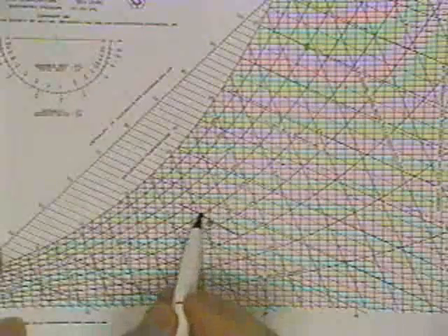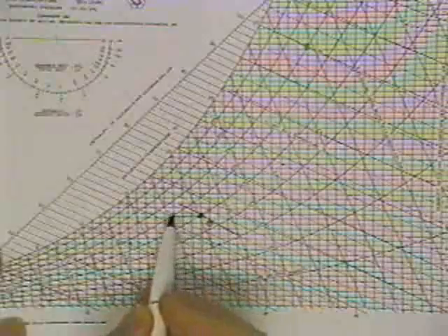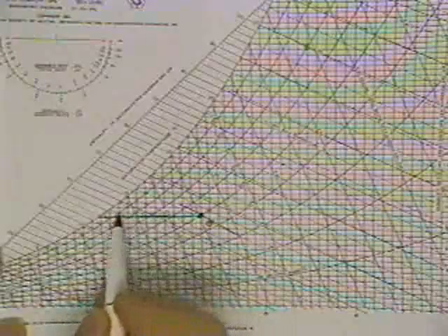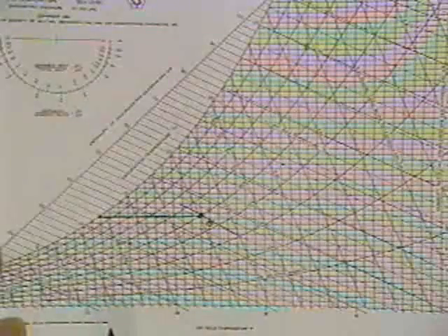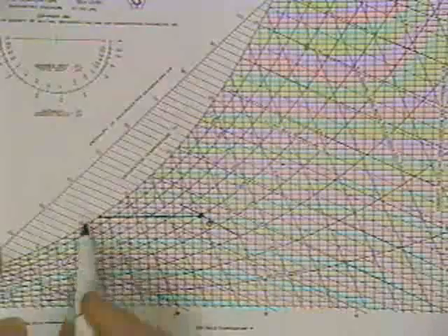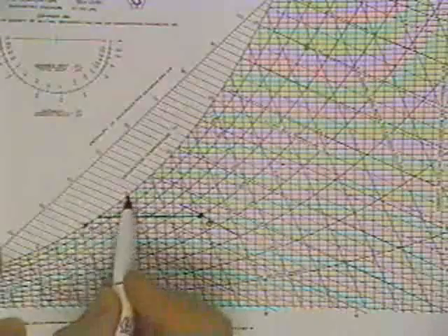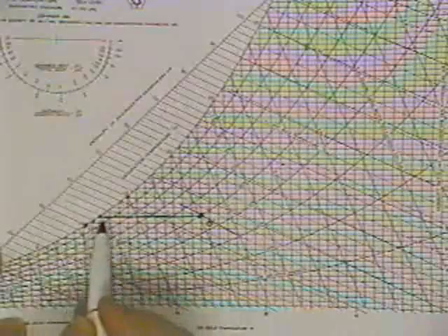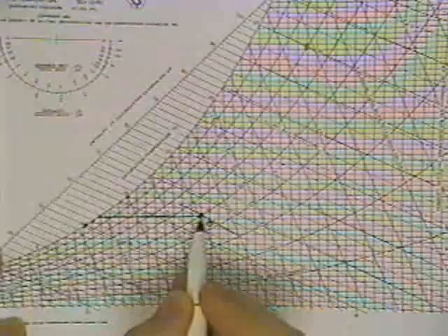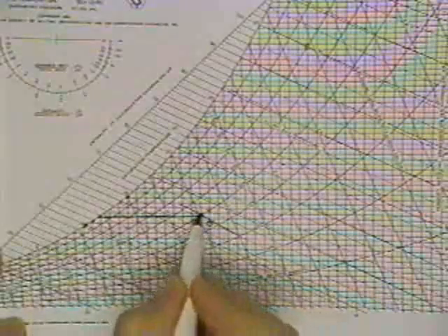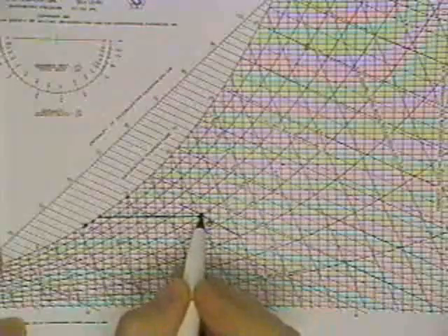The dew point is found from a horizontal line from your point over to the axis here, intercepting horizontally what the dew point is, and I read that as about 11.8. You can see where you are: this is 10 here, this is 15, this is 11, so this is about 11.8. So T dew point is about 11.8 degrees centigrade, and wet bulb is about 16.3 degrees centigrade.